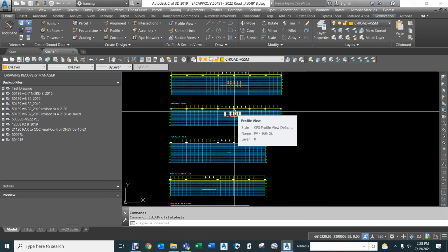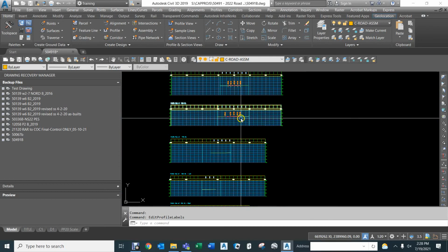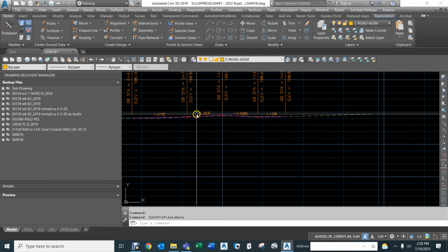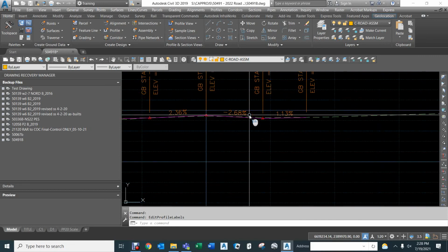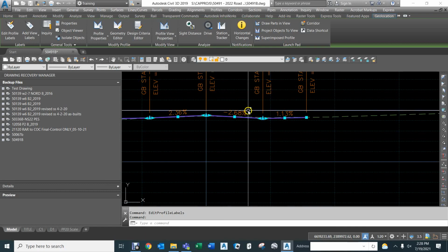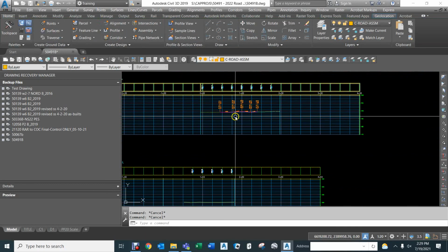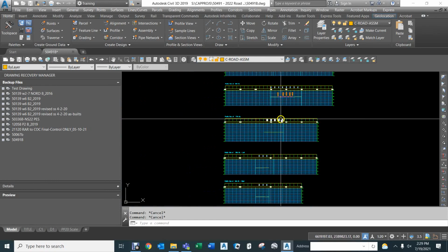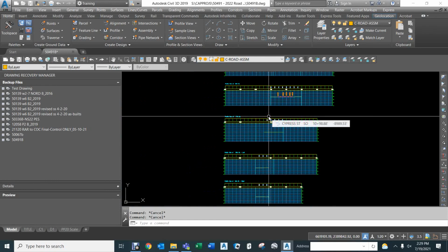Now it's ready basically to start the transitions through all of these intersections. We may have to pick some of these up a little bit to kind of ease through these. These are not bad at all because they both kind of lead up to it. We may want to lift this one up just a little bit just to be a little closer to 236, and ease this intersection, but technically we really don't have to. It's not that big a deal. So anyway, that's how you do the side street alignments and profiles.